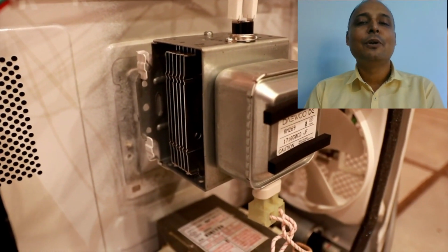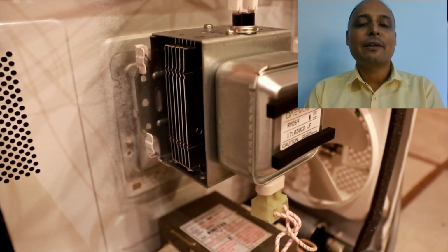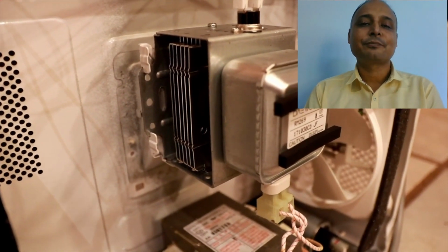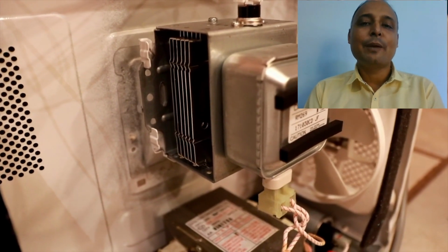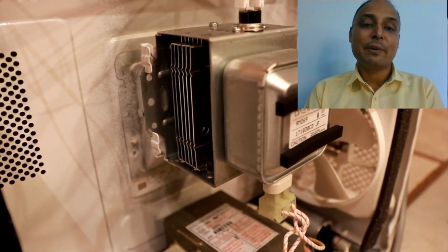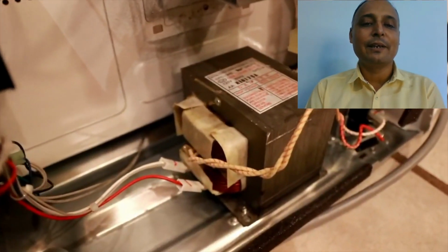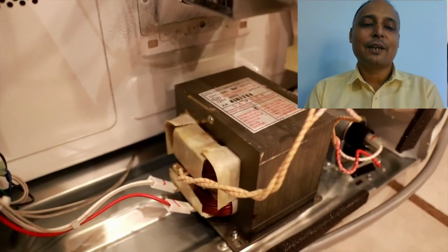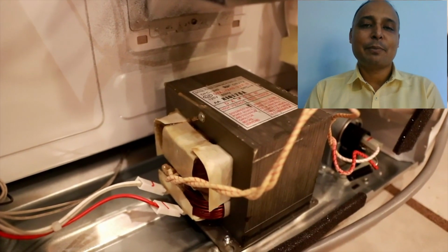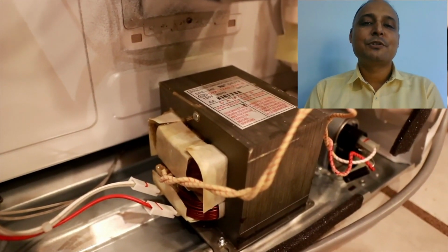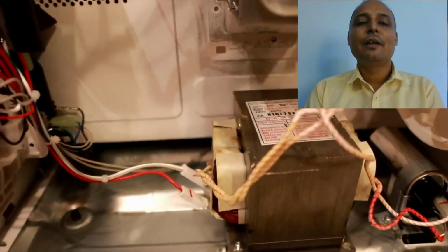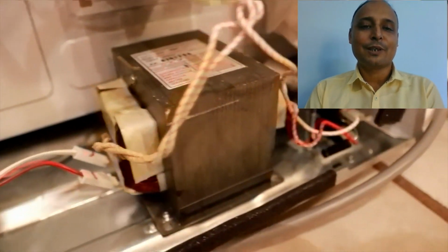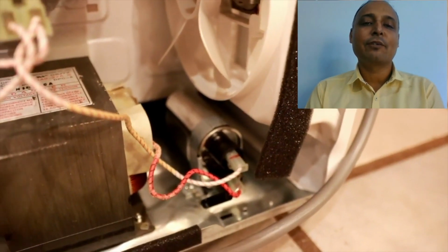In this microwave also, it is clearly shown that this magnetron is connected to the transformer placed just below the magnetron. And this transformer has windings called the primary and the secondary windings, which we can see very clearly in this transformer. And this transformer is also connected to a capacitor. Now this capacitor is also a component that sometimes gets damaged, so we need to check the working of both the transformer and the capacitor, whether they are working fine or not.